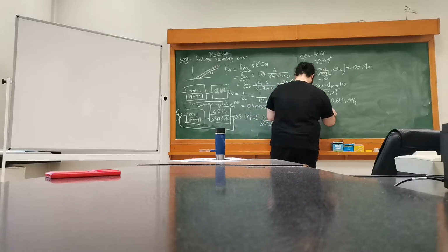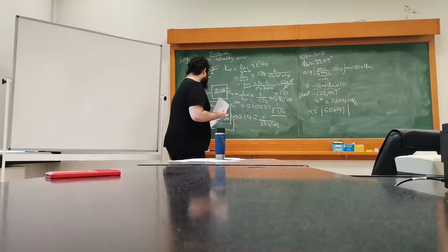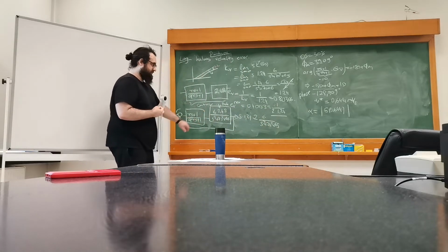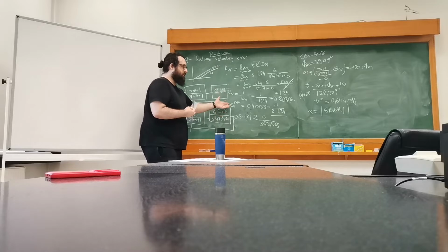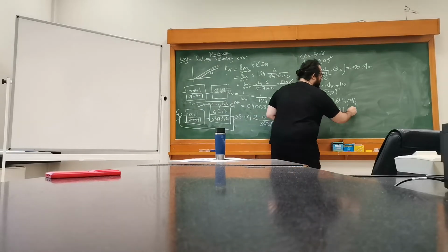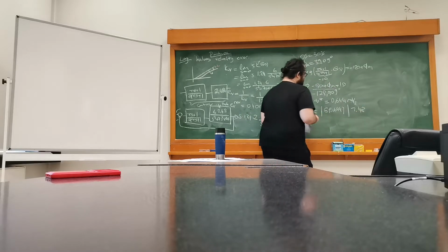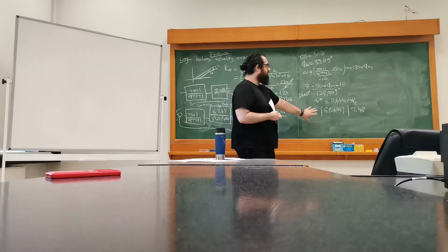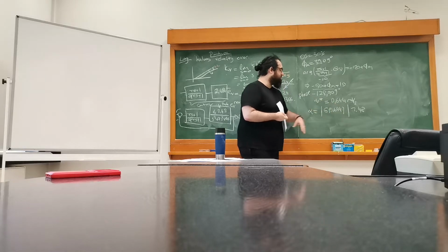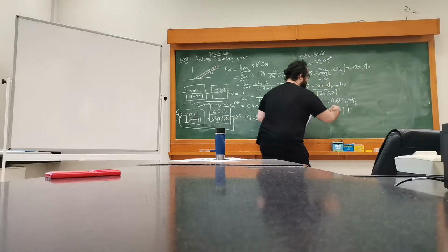At that point, 0.644. Now I write this like T, but it's basically the whole gain here at that frequency. So if you use an updated Bode plot, you can just use this. If you're using the actual Bode plot of the system, then you have to have 2.48. So it depends on your Bode graph. If you have the raw system Bode graph, this is the relation that you should use. If not, if you are using the updated one, then it's already included in the gain.